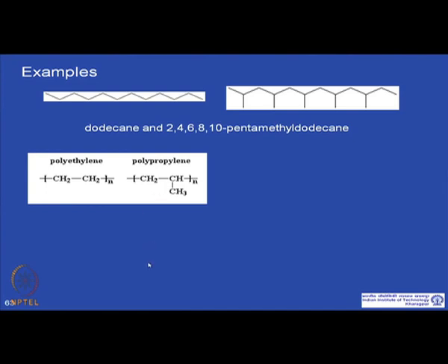immiscible blends. Another example we can talk about, say, bisphenol A polycarbonate and polymethyl methacrylate. If the length or the molecular weight of polymethyl methacrylate is high, then they do not form a miscible blend, whereas these two form a miscible blend as long as the molecular weight of PMMA is small, like an oligomer.